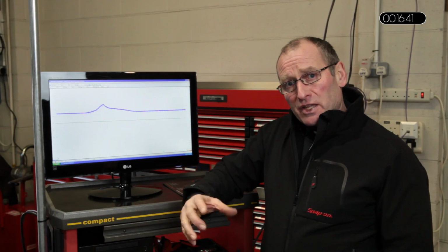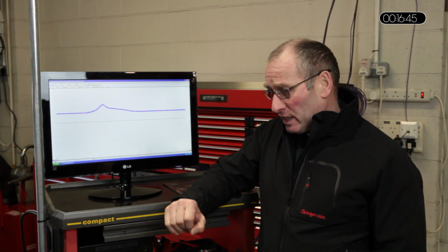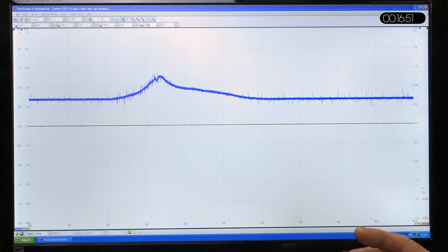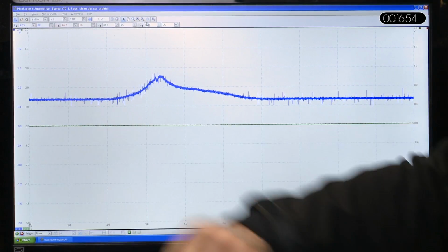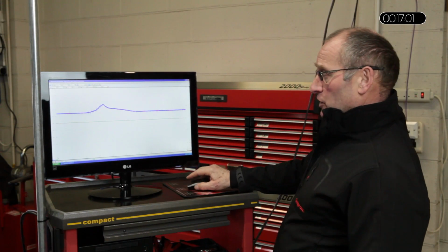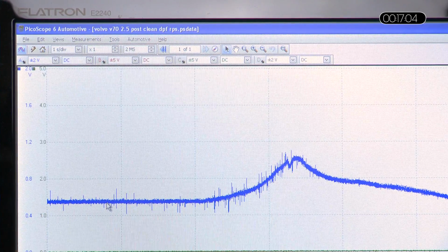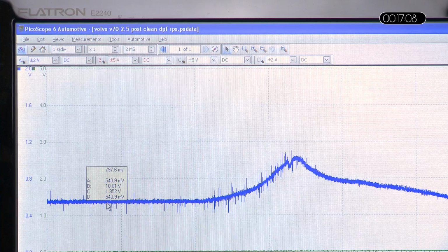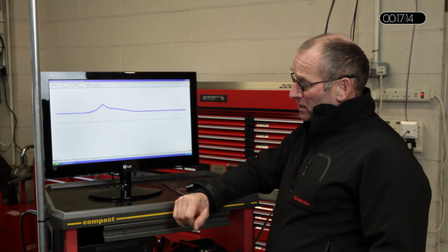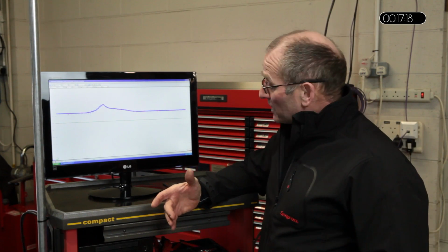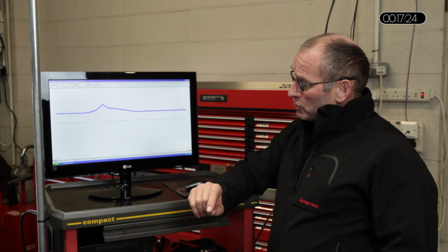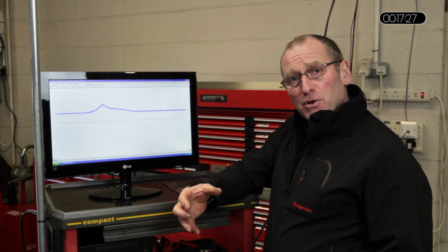We've seen, or starting to gather, some interesting information, patterns if you like, from this research, and what this image shows you is the voltage activity from the sensor with the engine at idle. So from the left, the engine is at idle, and we've observed from the multimeter this was about 0.6, 0.7, so let's just do a quick check. If I take a voltage reading, that measures 540 millivolts, 0.54 of a volt, excellent reading. We then increase the engine speed. Now obviously you'll appreciate that with increased engine speed you get an increase in the volume of exhaust gas, therefore the voltage, the pressure will increase, but it should not increase to a point where it forces a limp home situation.